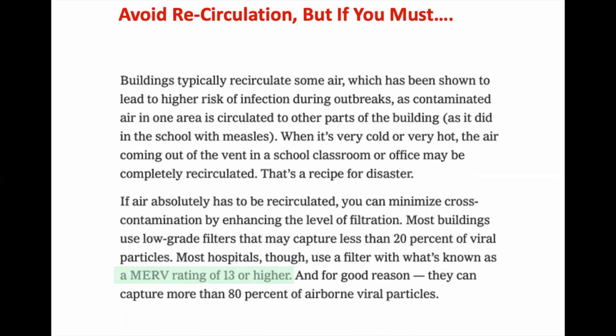You're also going to use bigger fans, whether the fans can even handle it. They're talking about adding MERV 13 filters. And if it's designed for a MERV 6 or a MERV 8 filter, you stick a MERV 13 filter onto that unit and the fans aren't going to operate. It doesn't have the capacity to even deliver that air. You're going to burn out the fans, have other issues.